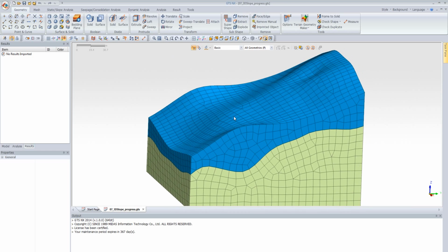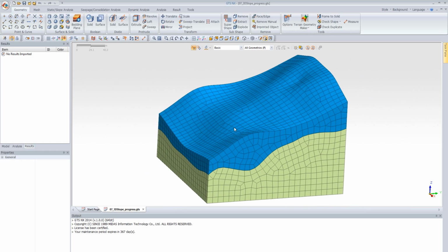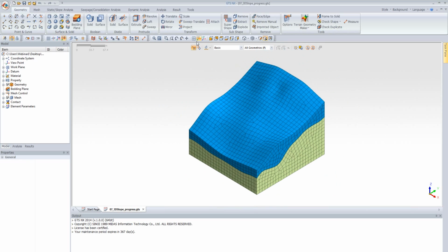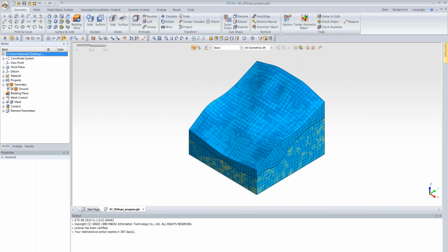So just using the 3D modeling aspect here, you can create contours that are very in-depth, very detailed. So for example, if I wanted to create a detailed 3D contour such as this, it's actually quite simple if you have a spreadsheet representing all of your values. So let's say, for example, I want to create a detailed 3D contour for the strata as well as the surface. So let's go back here, and let's turn the geometry off for now. Let's turn the meshing off.